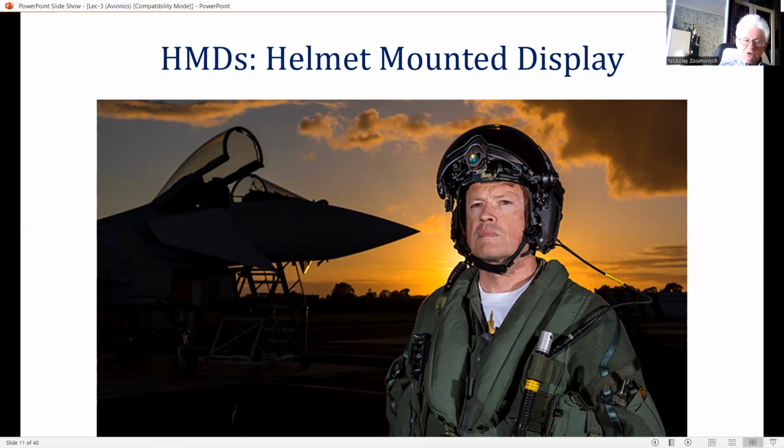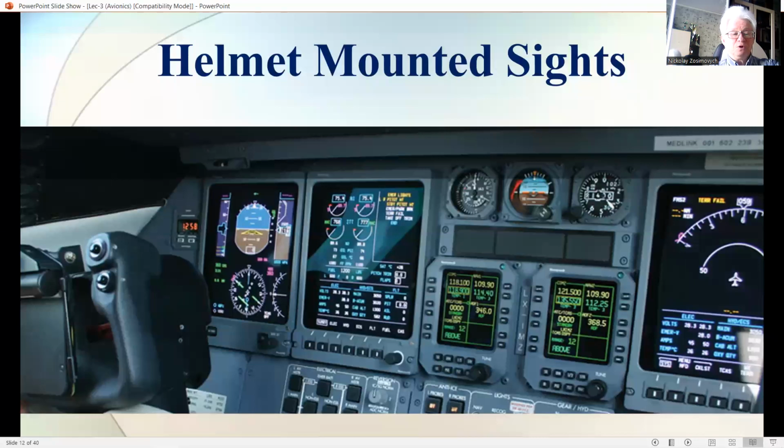It should be noted that the helmet will be pressed down on the pilot's head during high maneuvers as the helmet lining is resilient, and hence the need for a reasonable exit pupil so that the pilot can still see the display. Another subtopic in today's lecture is called the helmet-mounted sight.